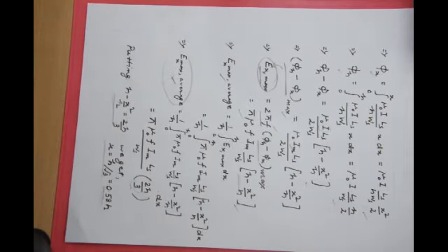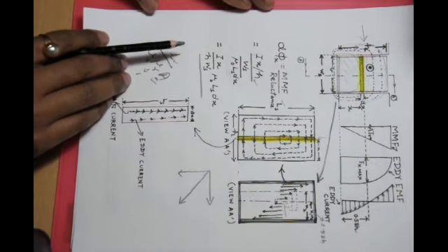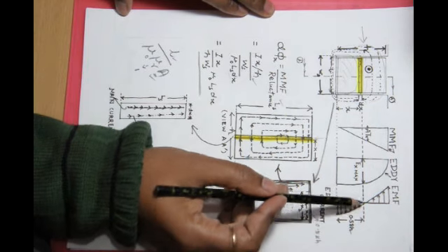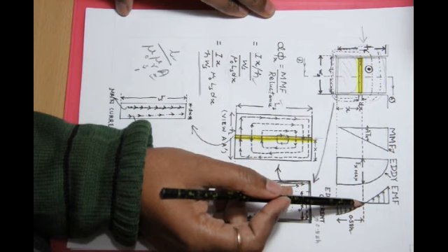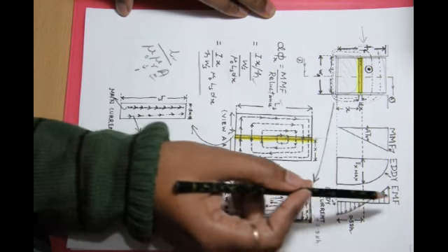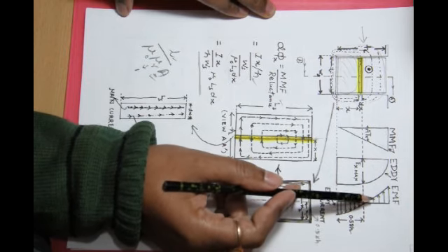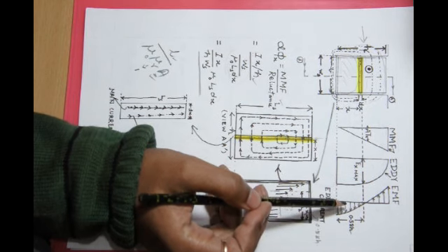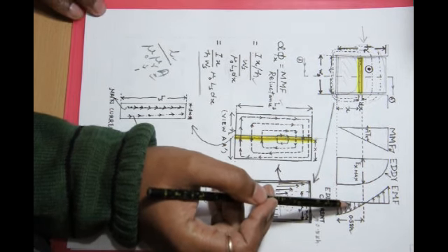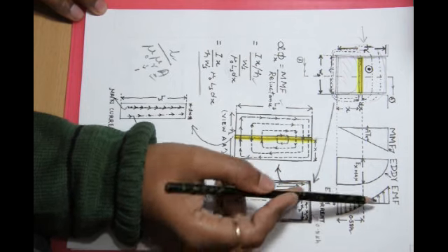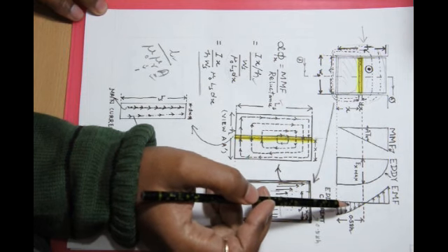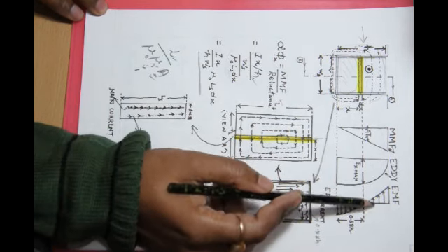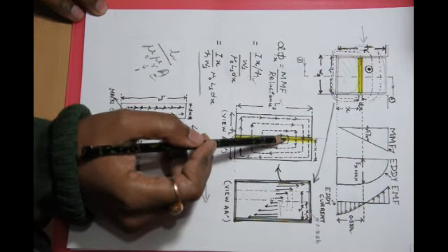If I show it on the diagram, it will look like this. At a distance 0.58 h, the difference between Ex max and Ex max average becomes 0, and moving downward or moving up, the difference changes its sign as we move up or down. Now this difference is responsible for the eddy current in this element or this element.